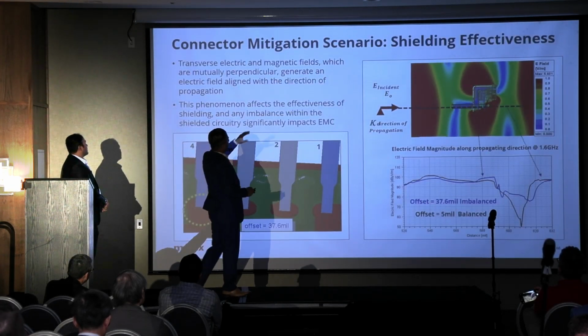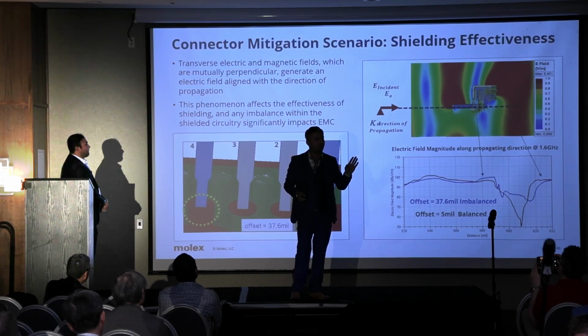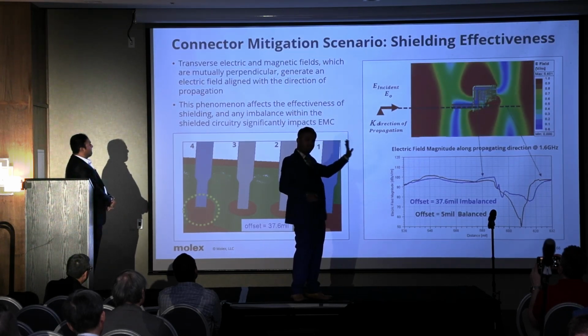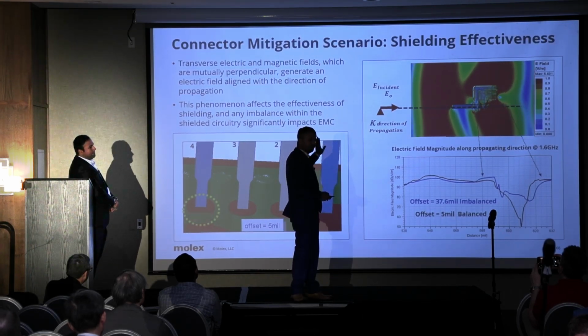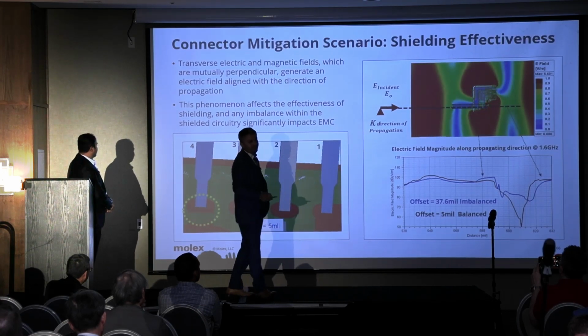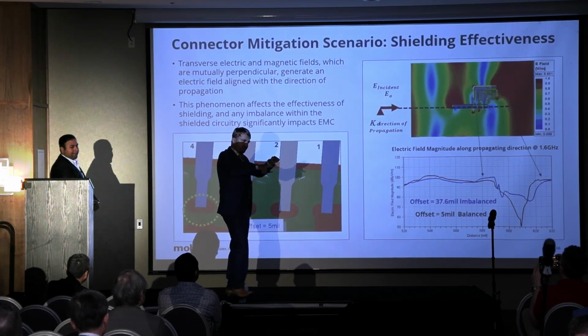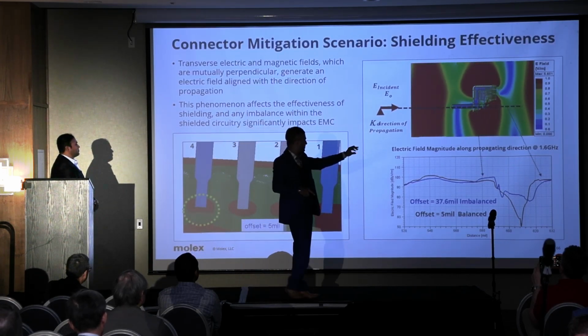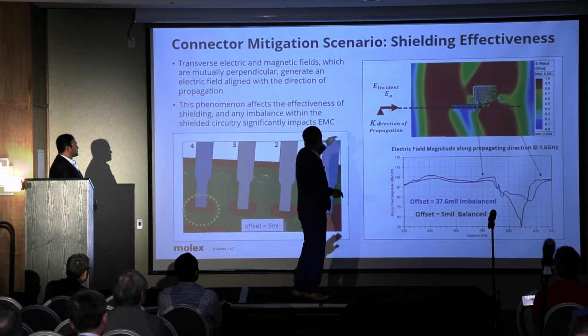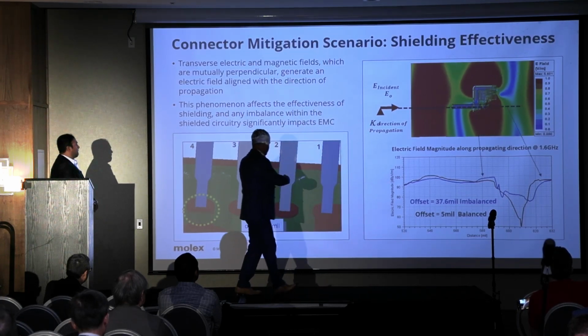Yeah. So we did a simple simulation here. We created a 1 volt per meter electric field, right? That is, K is the direction of propagation going towards the system, where I have an accidental antenna. Now, once it goes towards the system, we created an electric field monitor in our simulation platform. And in that particular region,